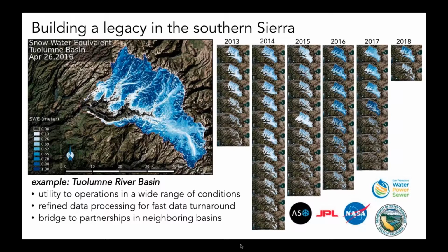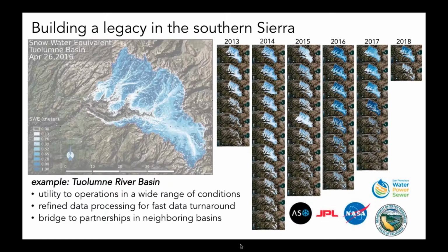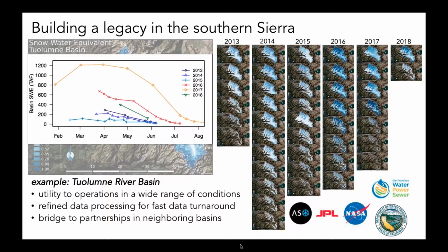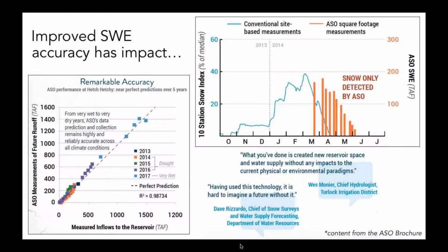So how do we add resilience to those forecast models that are suffering from changes in the environment? The first is to decrease the reliance on the historic record. So pull back a little bit and say, okay, well, we don't need to know 30 years of record for our statistics. We can actually look at the conditions on the ground now, improve the model realism such that they're responsive to those physical processes. To do that, we need to increase the availability and use of spatial data. So data that covers the entire watershed, not just a single point measurement. And this can be satellite, airborne data, as well as improved mesoscale and refined mesoscale weather models.